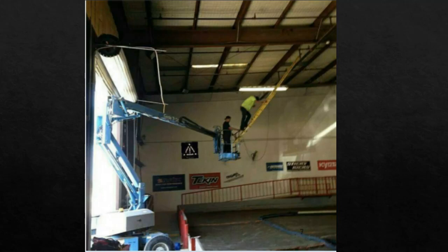Plus, when you get somebody on a ladder that's connected to one of these lift buckets, that's an awful lot of strain being placed on the lift bucket itself and on the outriggers that you might or might not have down there, or the counterweights keeping that lift bucket upright. So this is a recipe for an overturned bucket, for the ladder slipping, and for something really devastating happening.